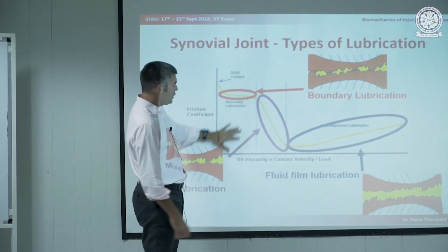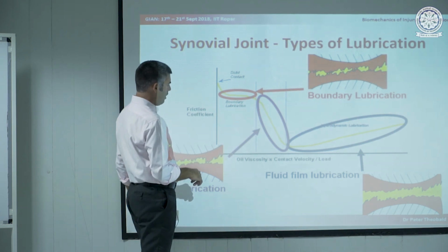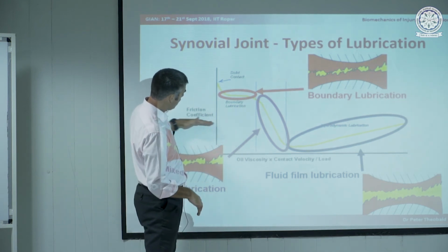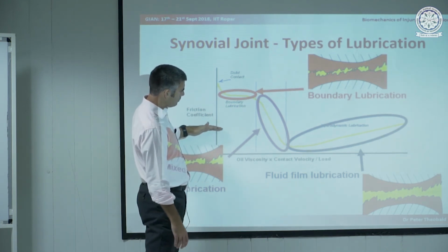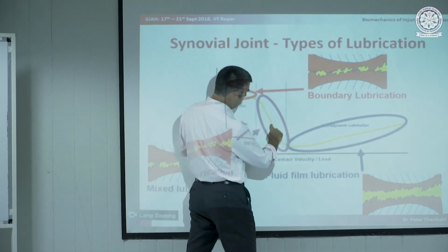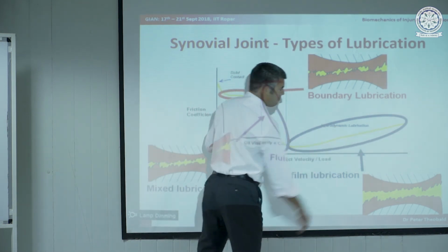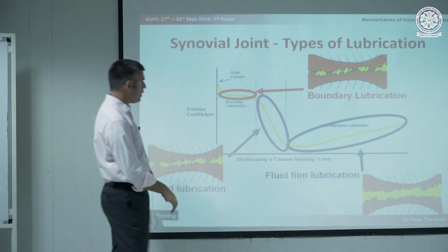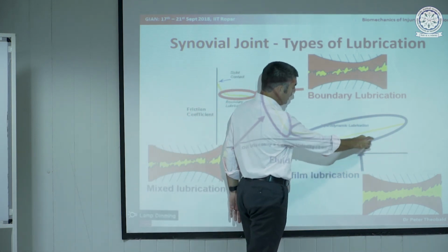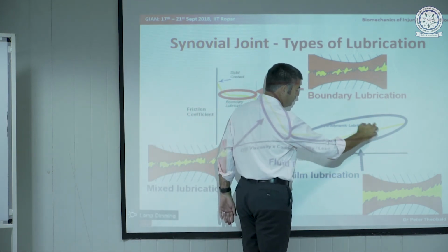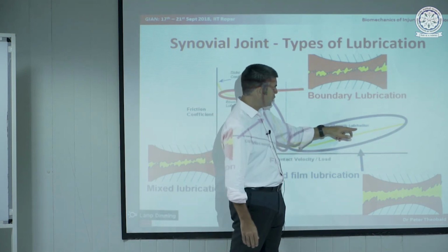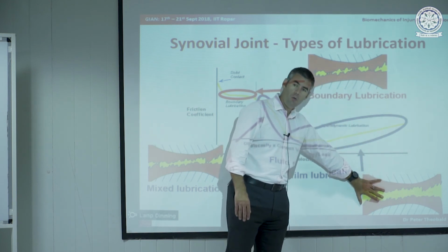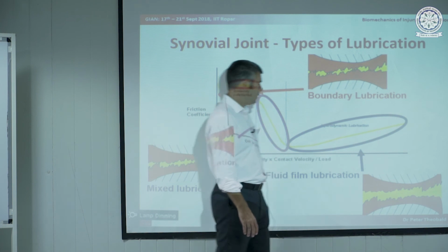And indeed, engineers have looked at all these parameters. They've looked at the type of coefficient of friction that the human body gets, and it's notionally about here-ish on this graph. So it could be that we're somewhere here, or somewhere kind of here-ish. They've seen that it lasts 70 years, so outside of the realms of anything else. And so reasonably, you'd expect it to be in hydrodynamic lubrication, which you can't see because that circle's on top of it. So that is where you have a full layer of fluid that separates the two surfaces.